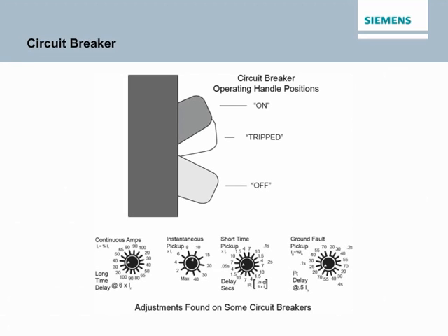Another device used for overcurrent protection is a circuit breaker. Although some circuit breakers do incorporate fuses, most do not. But, like a fusible switch, a circuit breaker provides overcurrent protection and a manual means of controlling power distribution. When an overcurrent occurs, the circuit breaker trips to remove power from the circuit. The greater the overcurrent, the more rapidly the circuit breaker trips. Once the overcurrent condition has been corrected, a simple flip of the breaker's operating handle restores the circuit. The ability to restore a circuit without replacing a fuse is one of the key advantages of a circuit breaker.